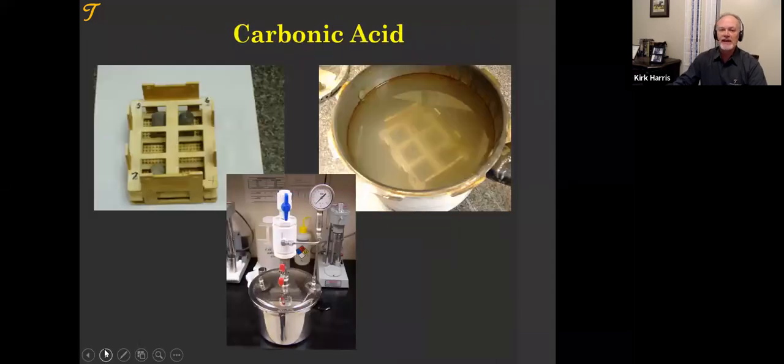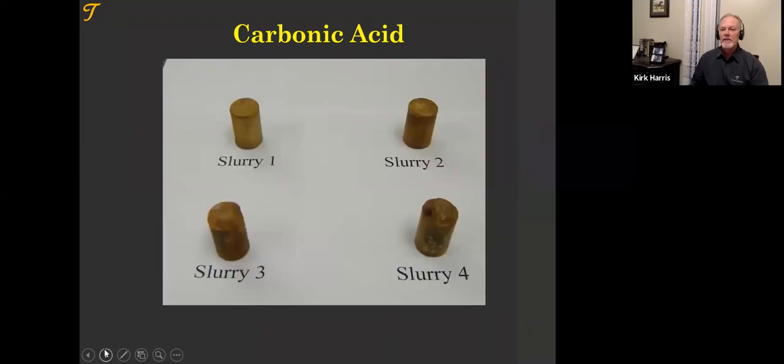I'm going to show you 3 acids and how we've tested them. Much of my testing has been for this. As I've worked for various companies, we've tested acid solubility many times in the lab. Here we're testing in a pressure cooker, constantly feeding in the CO2 and creating the carbonic acid. We test specimens, and what we achieve is more of a dissolution of the calcium out of the cement, out of the Portland cement. It more brings it out of solution so that you get a pitting.